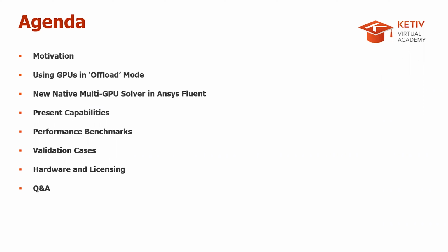So for today's agenda, we'll start with why look at GPUs versus CPUs, which is the more conventional way of parallelizing your CFD simulations. We'll talk about the existing GPU technology already present in the Ansys environment, which we basically refer to as using GPUs in the offload mode. We'll then talk about the native multi-GPU solver, which is fairly recent.